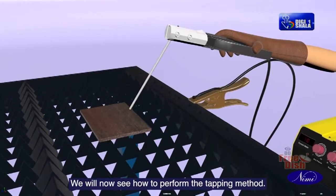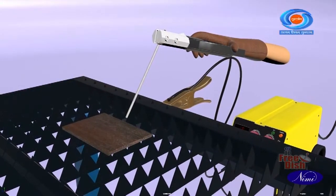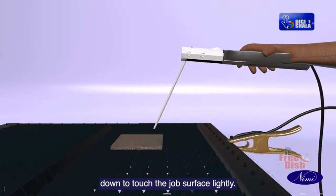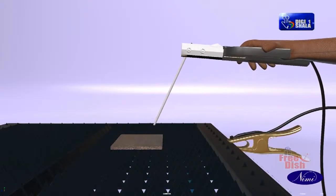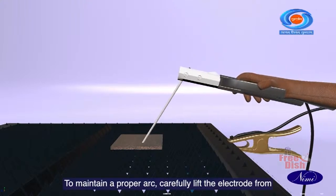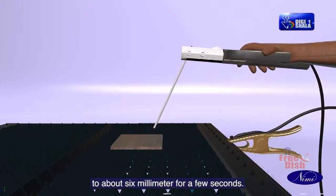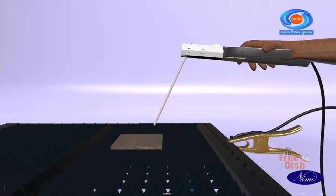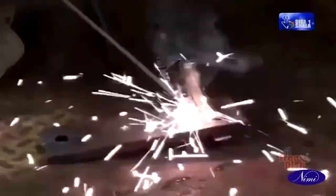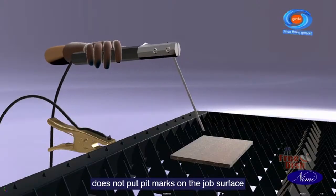We will now see how to perform the tapping method. Strike the arc by moving the electrode down to touch the job surface lightly. To maintain a proper arc, carefully lift the electrode from the surface to about 3 mm and then lower it to about 6 mm for a few seconds. The tapping method is most recommended as it does not put pit marks on the job surface.